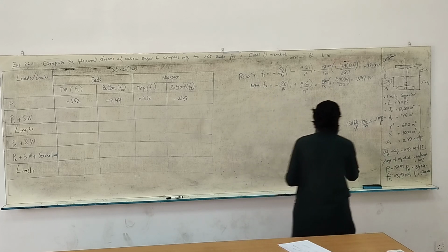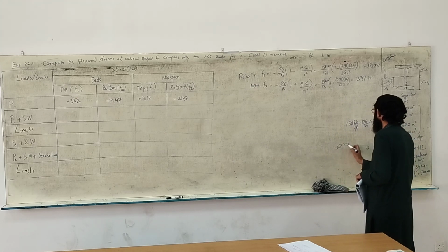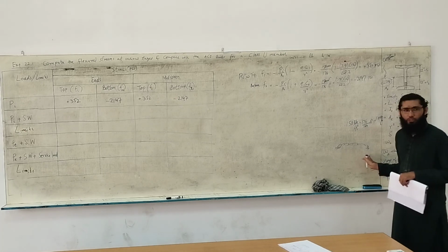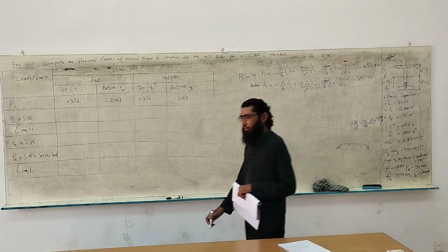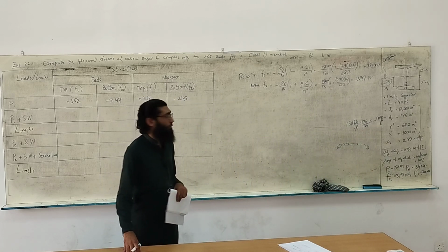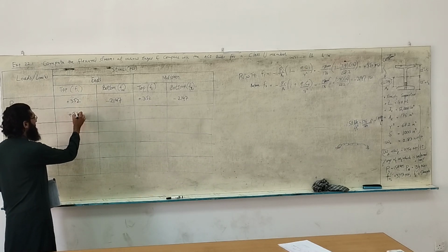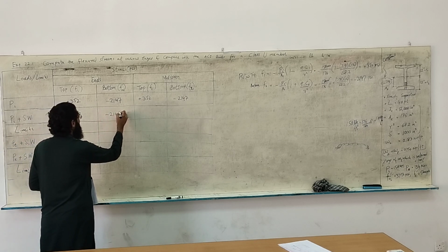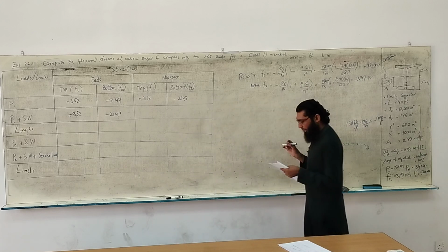If it is a simply supported member and you apply a uniform load onto it, the moments at the ends will remain zero. If the moments are zero at the ends, the flexural stresses will also be zero at the ends. So no effect at the ends. You will just replicate these numbers from the previous row.